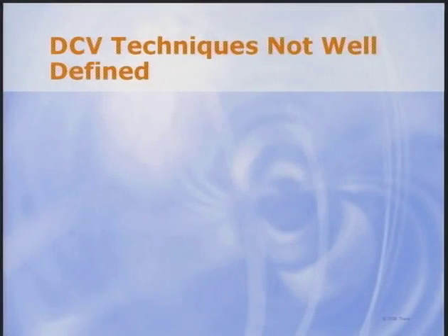Standard 62.1 is also very general. In fact, it's even more general. As Dennis pointed out, Standard 62.1 allows dynamic reduction of outdoor air rates not only when occupancy is below design, but also if any design condition used to determine the outdoor air rate changes. Dennis discussed various control options that designers might use, but the most common dynamic reset approach is demand control ventilation, and is the first application example listed in section 6.2.7, although the term demand control ventilation is not used.